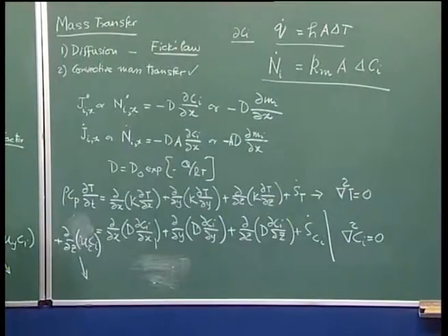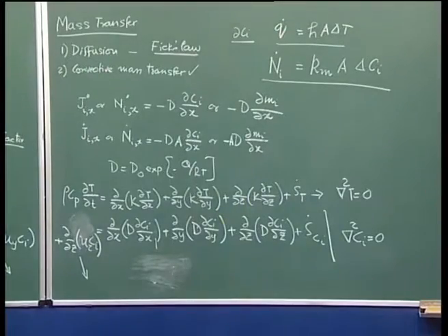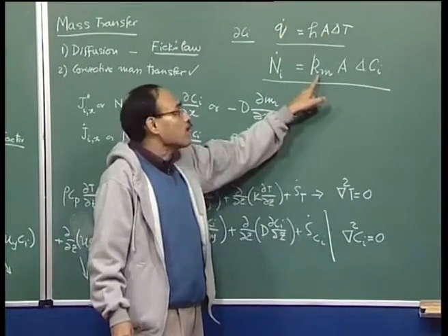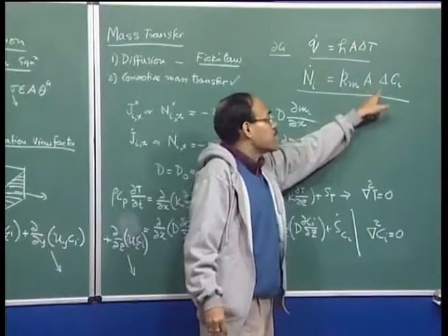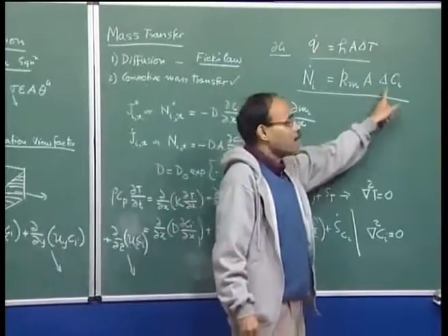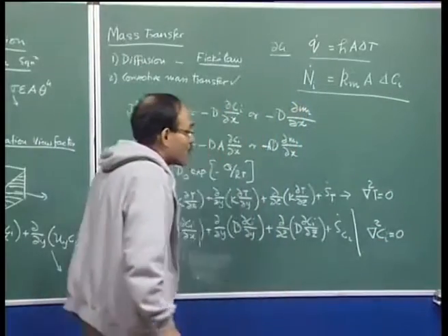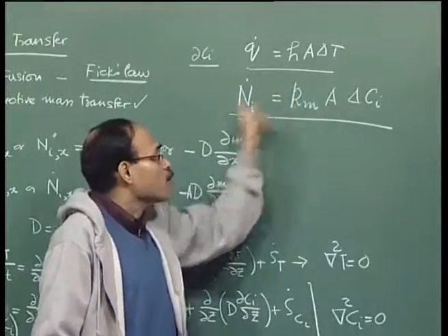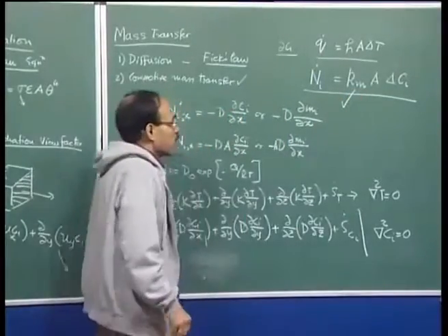in the system itself. So, in convective mass transport, the main objective for calculation of mass transport rates boils down to the calculation of the convective mass transport coefficient. If you can somehow calculate Km, in that case delta Ci will be known to us, and this is very interesting. The concepts of thermodynamics really come in here in order to find out that delta Ci, and I am going to explain to you subsequently when we talk about metallurgical kinetics. The area which is relevant to transport will always be known to us, and therefore we should be able to calculate without much difficulty the rate, provided we know the mass transfer coefficient.